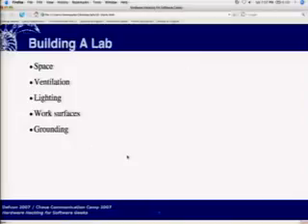So one way to start is an ESD mat and some grounding bracelets. And maybe a coat if you've got cats or whatnot, because even if you've got fur on the outside of the coat, it's of a material that's going to keep the static from building up on the fur and not going to short your devices. So the coats are actually fairly useful, especially if you have pets.